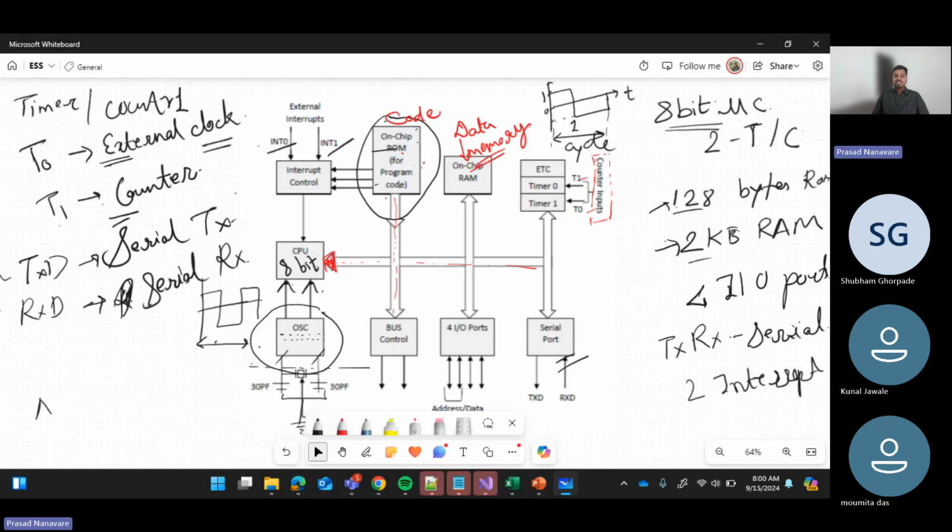So that is achievable with the help of RTC, real time clock. But how will it understand this has happened? It will understand with the help of ISR, which is called interrupt service routine. Once a particular event has occurred, it understands that I need to jump to the interrupt service routine now, complete that task, and then continue with the rest of the stuff. Basically, I'm doing my task, somebody is interrupting me, then I'll attend that person and then again continue my task, right?